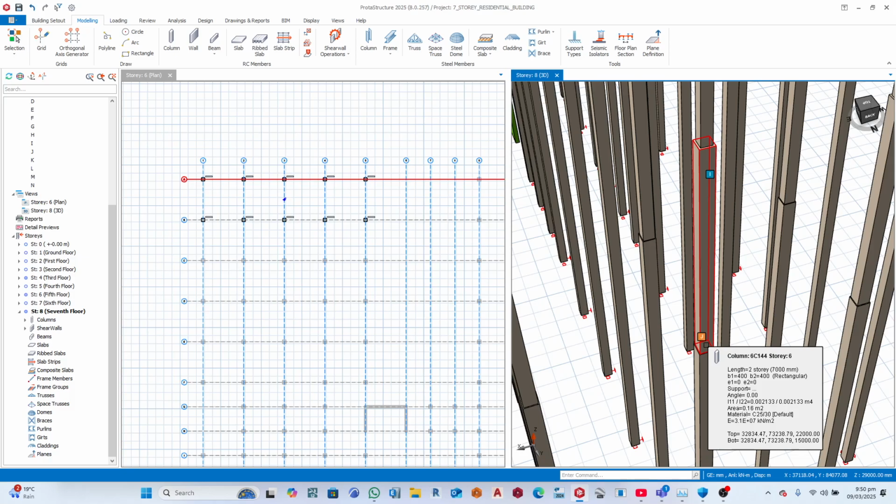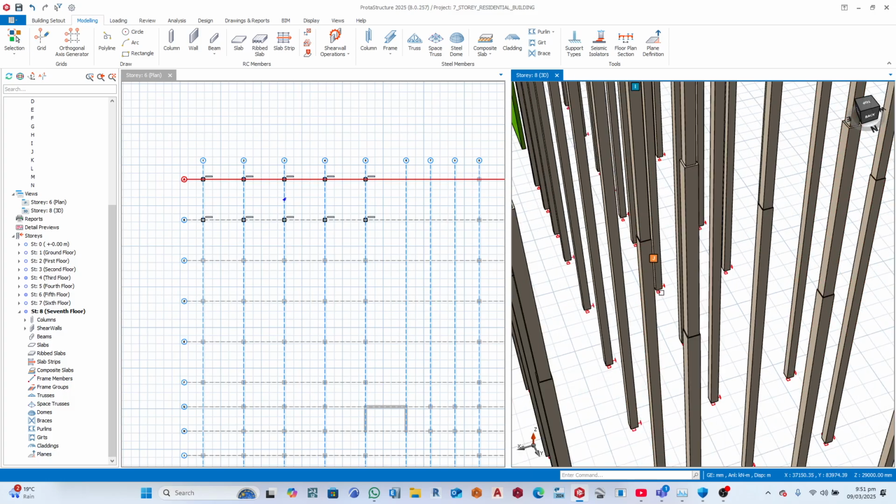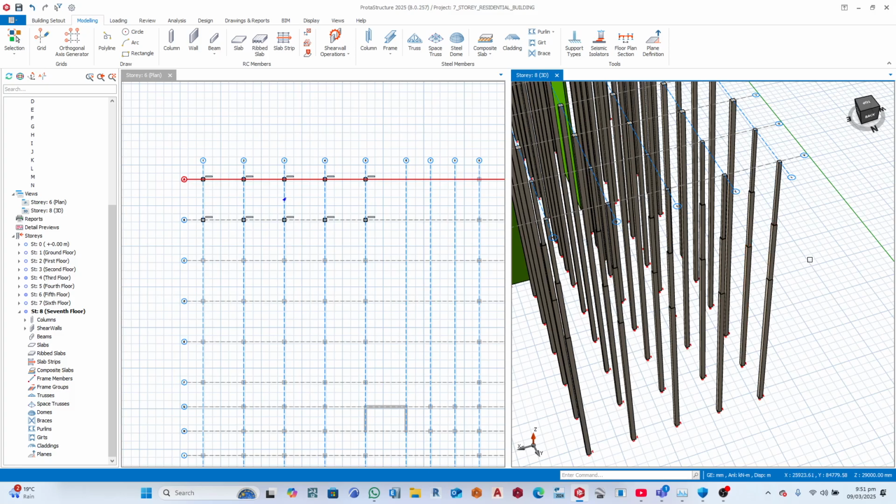So that's essentially why, like he pointed out, at the King's Hospital we noticed that as we were going up, the columns were reducing in size. That is the reason why they were reducing, because the building is loaded from up coming down. So from up, it has got minimal axial load acting on it. As you go down, it's taking its own axial load together with what is coming from above. It's handling that, transmitting it down. Then the third one is handling its own axial load from the floor plus the two other floors on top. Yeah. I hope that's clear.